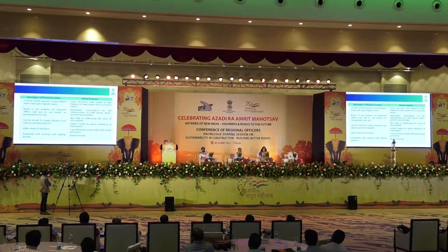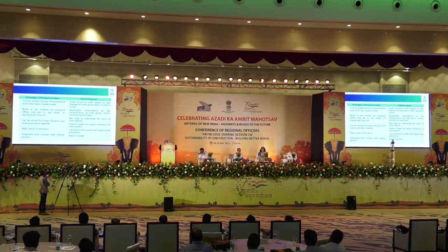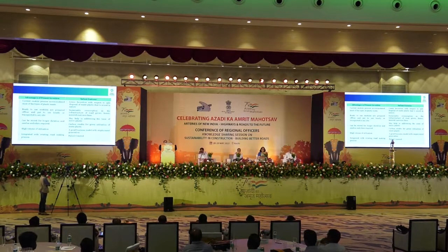You can take it, prepare it someplace and store it, and then wherever it is needed, it can be moved there and transported. It can be stored for long duration, so not in utilization. And of course, as I mentioned that almost a kilometer of your road utilizes 50 metric tons of waste plastic, which is very good. Integrated with existing road system, so it can be utilized either for concrete roads or for bitumen roads. So it is irrespective of road material what you are going to use can be used here. But of course, as mentioned, initially we should be trying those at service lanes and the roads which are having low traffic areas.